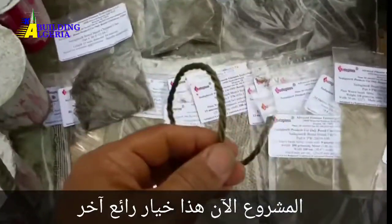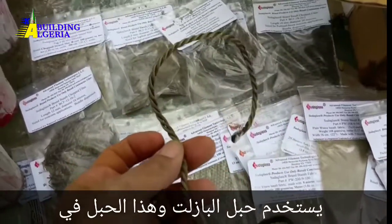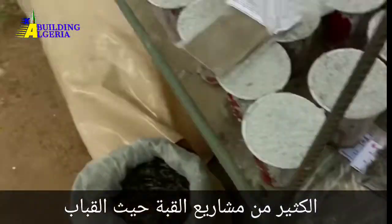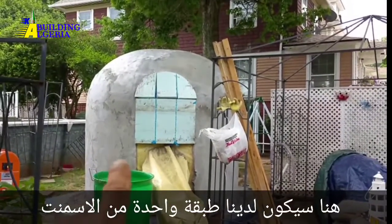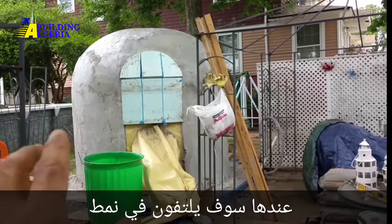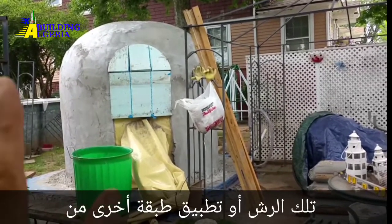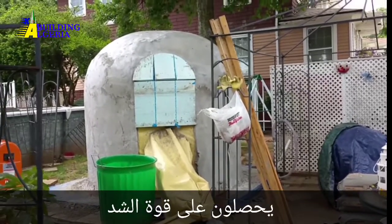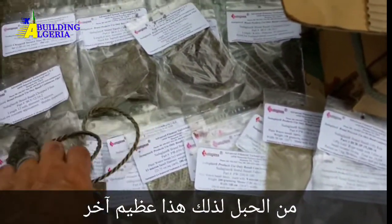Now this is another great option they have here, this 3-ply rope. It's basalt rope, and this rope is used in a lot of dome projects, where domes similar to this dome that I'm building here will have one layer of cement put on, then they'll wrap around in a pattern with the 3-ply basalt rope. Then they'll spray or apply another layer of cement on top of that, and that way they're getting their tensile strength from the rope. So that's another great product.